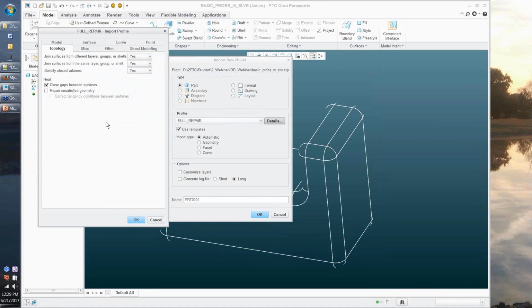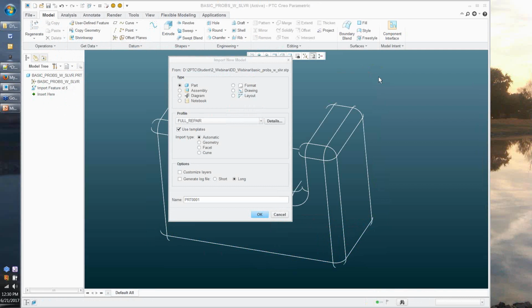I have to be very careful about molesting the import file a little bit and turning it into something it's not. So I am reluctant to deploy that setting under all circumstances because the surface topology will be affected by these settings. I am very reluctant to do the full repair that I have here. I will always import a file with my no-touch setting and see what I am dealing with before I would attempt to do one of these full repair imports. But those are the big ticket pages and the changes that I have between my no-touch setting climate and my full repair climate.